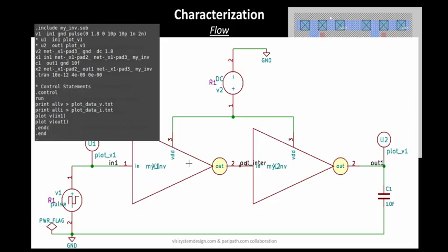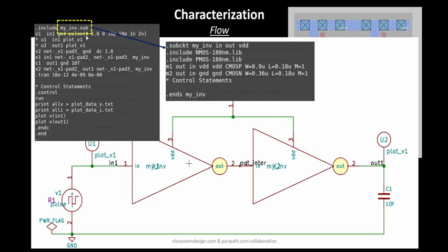We have extracted all of them in terms of a spice netlist. In the spice netlist, you will see a lot of capacitances and resistances. Okay, it's not evident over here, but in a real extracted spice netlist out of the layout, you will see a lot of resistance and capacitance statements. So that's called an extracted spice netlist. Finally, you have the inverter subcircuit.